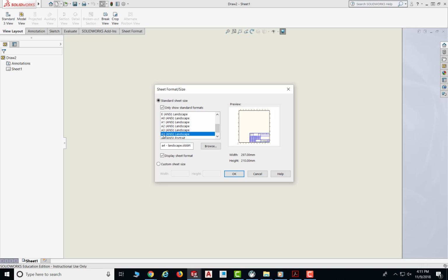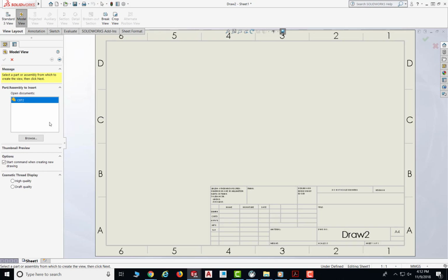The sizes are similar, but not exactly the same. At this point, we're going to use A4. So we have portrait and landscape. Let's choose landscape and say OK for that. Just to let you know, the size is 297 by 210, and say OK for the paper size.